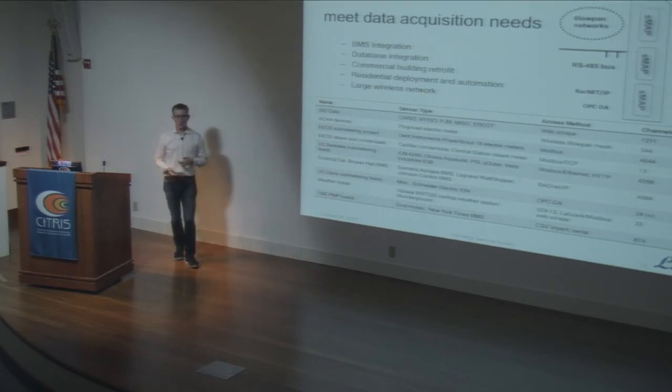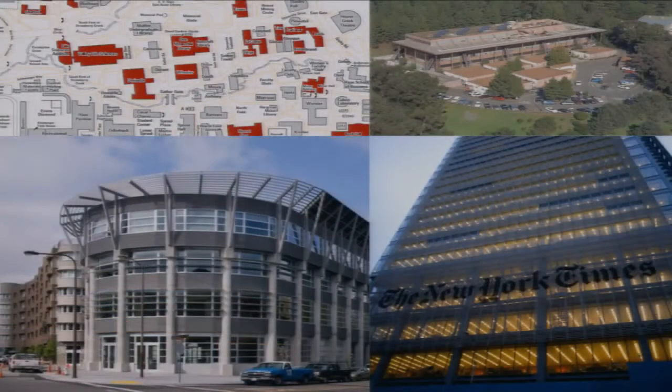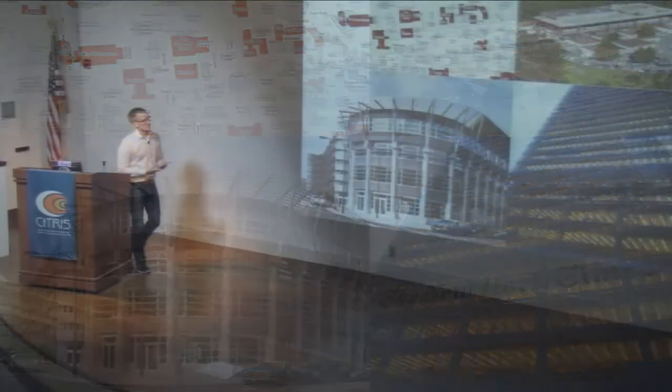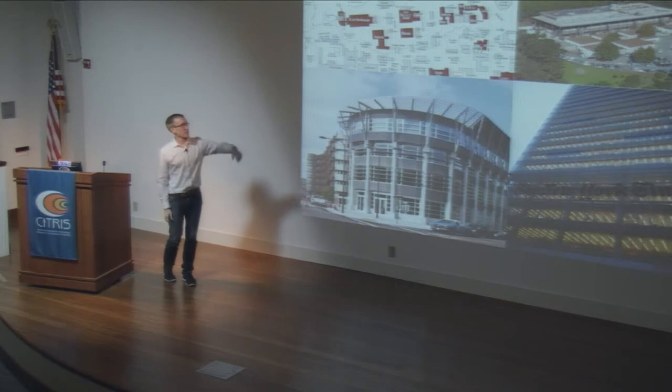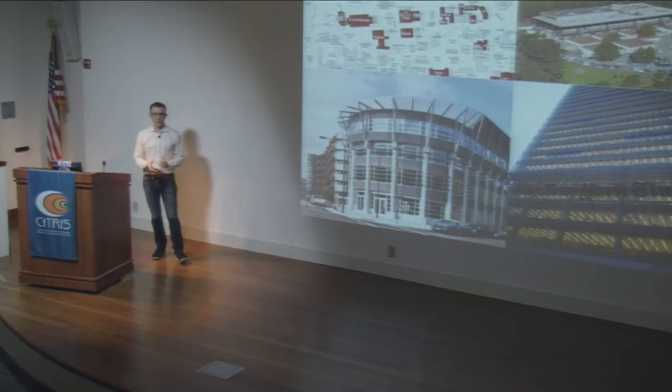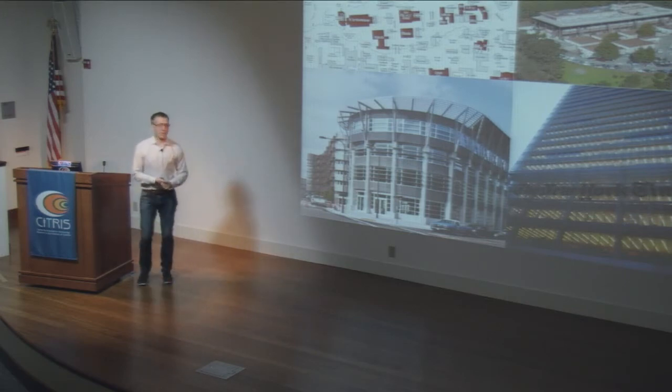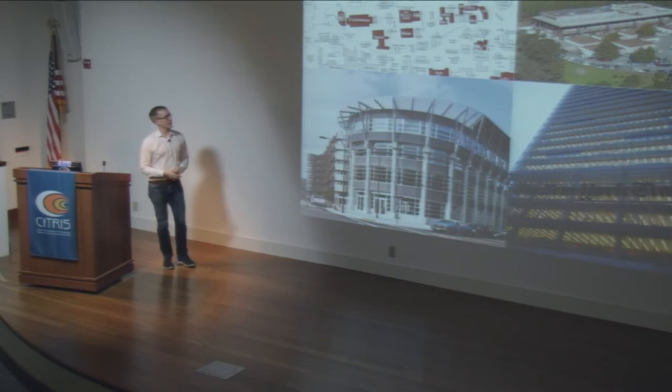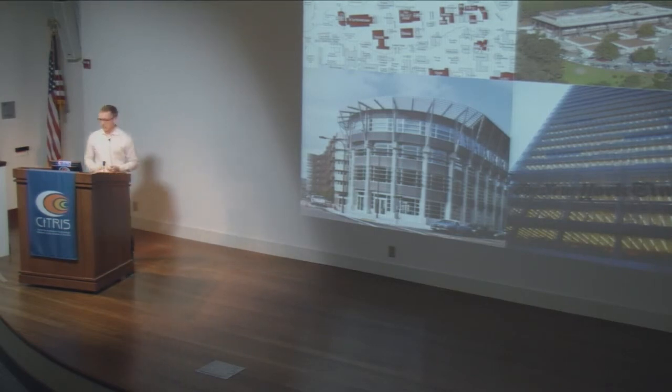And then we've done some more hardcore industrial protocols like OPC, which is OLE for process control. It was considered very good in 1995. And then also sucking up data from a variety of other building management systems. And the nice thing about working in buildings is, like I said, they're also often really pretty. So here are some gratuitous pictures of buildings we have data from. The David Brower Center is running a BACnet stack on Windows. New York Times exports CSV files. We had a giant deployment of 6LoWPAN, which is a low-power IPv6 mesh networking standard, in Building 90 that was sucking down a few thousand channels of data from 500 motes, and then a bunch of buildings on campus.